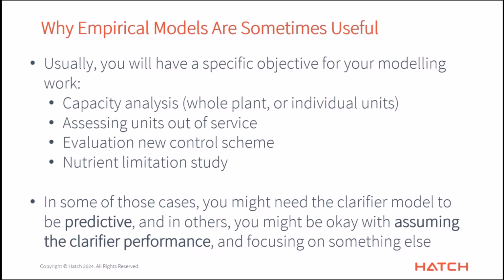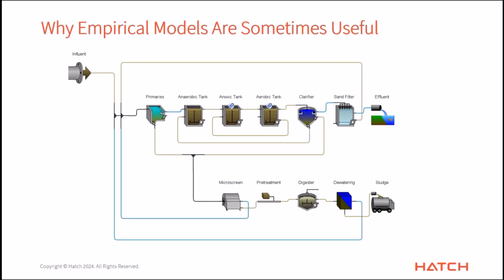You need to say, when it's loaded up a lot, I need to show that it's not going to remove as high a percentage of solids as it would under low loading, right? But a lot of the other time, if I'm really looking at the aeration capacity analysis, or I'm trying to study potentially the sophistication of my internal mixed liquor recycle or how the alkalinity is affecting my nitrification, that's not really a function of what's going on in the clarifier for the most part. I might be fine with assuming that my clarifier is going to work okay. So therefore, I can pick one of the simpler models, just set it and go, and then really focus my time and effort on the biological part.